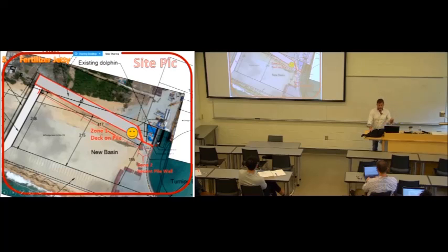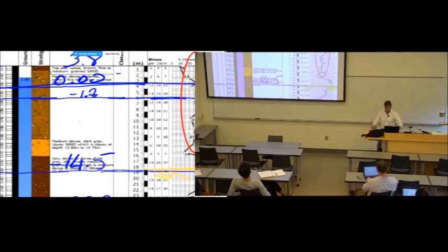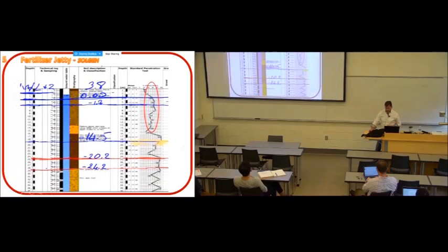Now for you to know, I'll show you so you can visualize the weight that is involved. But let's start with the soil. Remember? So we go back to the soil data. Look at the SPT values, upper 30s. And these are pretty good values for sand by the ocean.